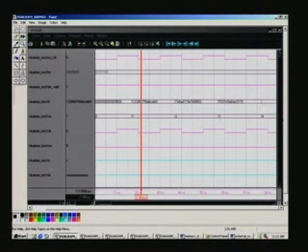D0 output will come only later on, after having written all, while writing the next block of data, then we will simultaneously read. So after 8 clock pulses or so plus pipelining, maybe 10 clock cycles only, you may start getting it, and I will zoom this.